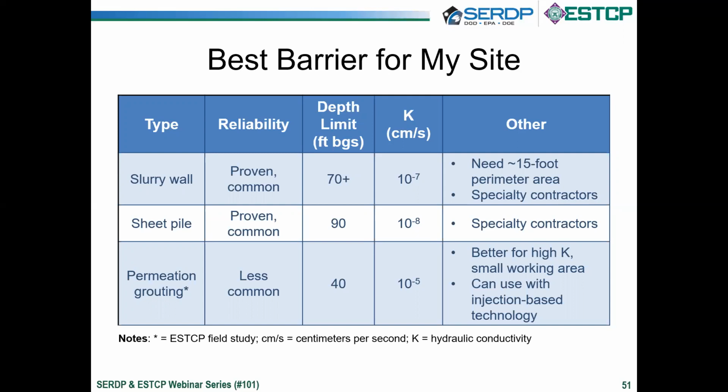It requires a smaller working area and can be used with injection-based technologies. It's also more applicable for higher permeability sites, has a depth limit of about 40 feet, and can create wall hydraulic conductivities of about 10 to the -5 centimeters per second.